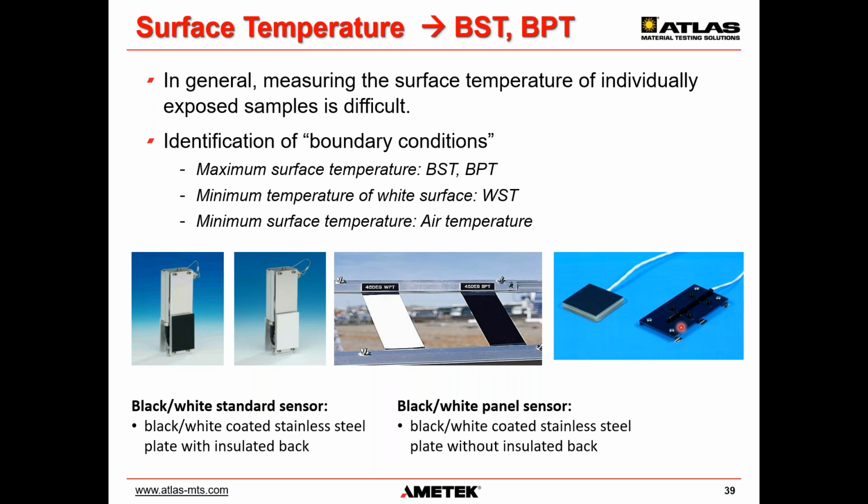ISO standards historically prefer the black standard sensor. Most standards today allow both options, but the results may be different because of the unknown temperature difference. So be very careful when you test according to a standard in selecting the right sensor type. That's very critical for the degradation.